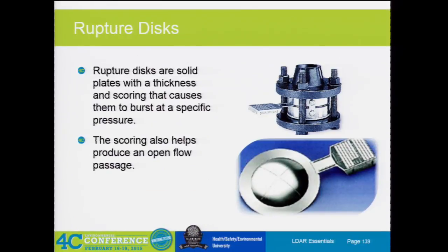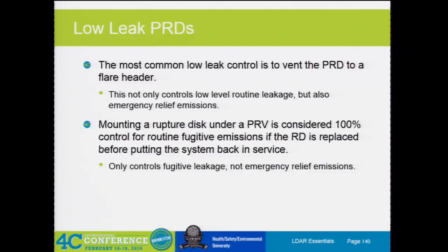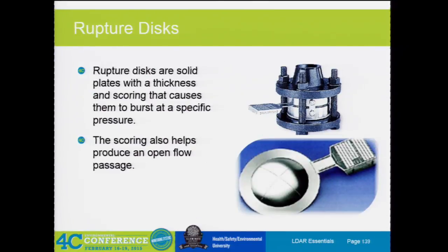The rupture disc, these things pretty much guarantee you'll have a seat on your valve, and you shouldn't get anything to leak past your rupture disc unless it's no longer there, ruptured. And then you have your PRV after that. So you'll see them in conjunction with each other. Yeah, the orifice plate's like a flow thing, right? So this one just actually stops it altogether, right? It has a breaking point.